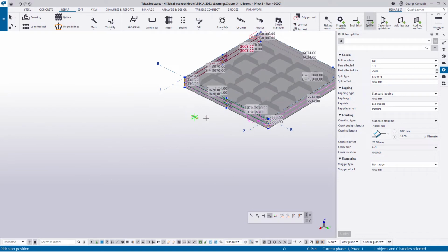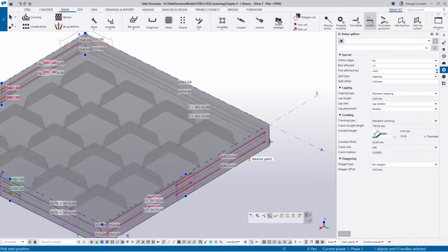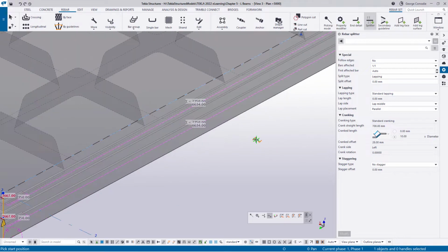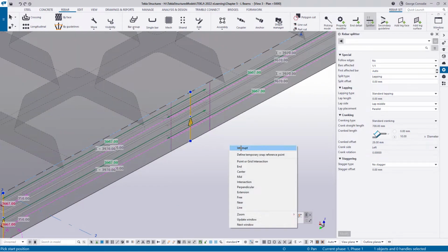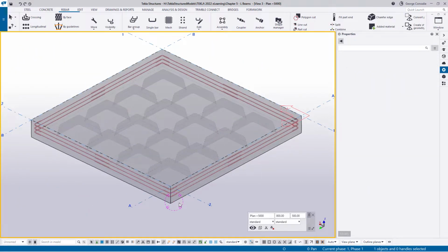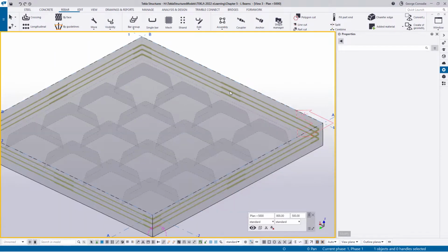And then this edge. And then I think we're on the second last side. So this side, that's the middle, that is the corner, and then the last face is this one. Yeah, there we go. And now that we've split all of the sides, we're basically left with a perimeter bar that looks like this. We're lapping in the corners, but we're also lapping midway, which gives the guys on site a smaller bar to deal with, an easier bar to fix.